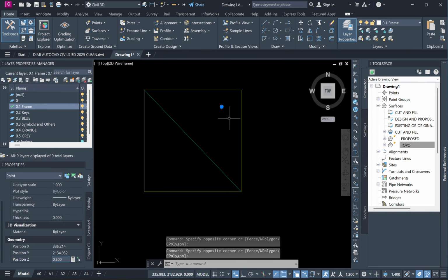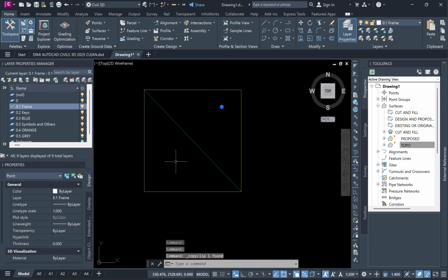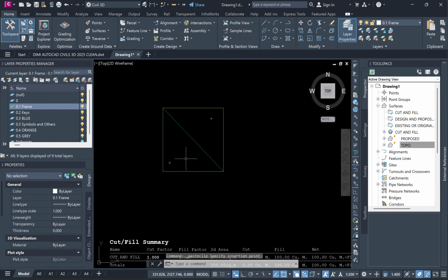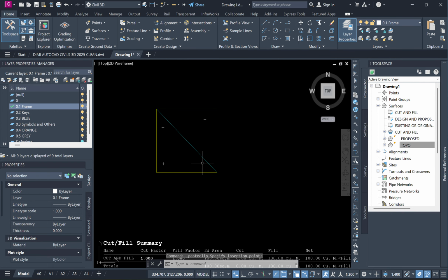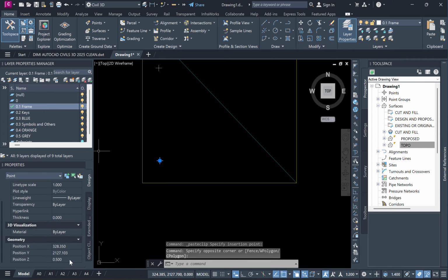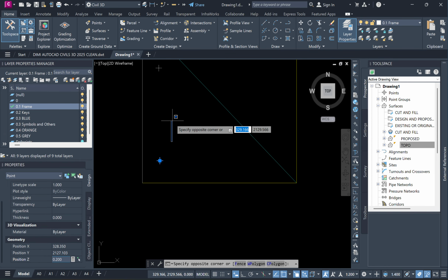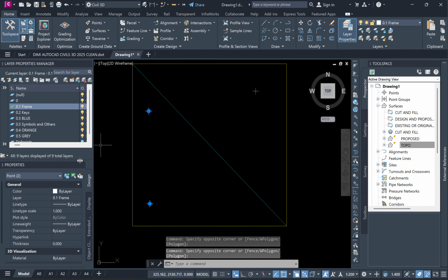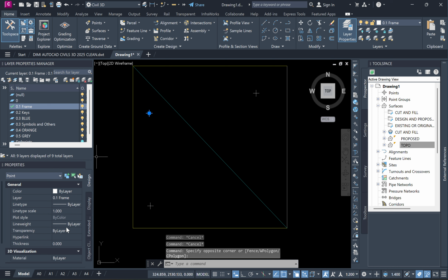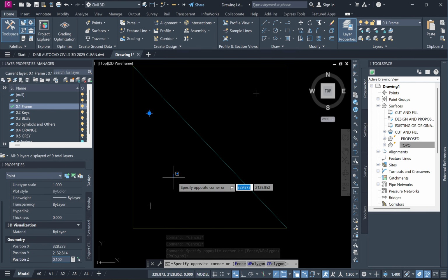just like that. And we can copy, so I'm gonna press Ctrl and C, Ctrl and V, okay, Ctrl and V again. Just gonna copy a couple points randomly. We're gonna change this one from 0.5 to 0.2 elevation, okay, and this one, to 0.1 elevation, just like that.